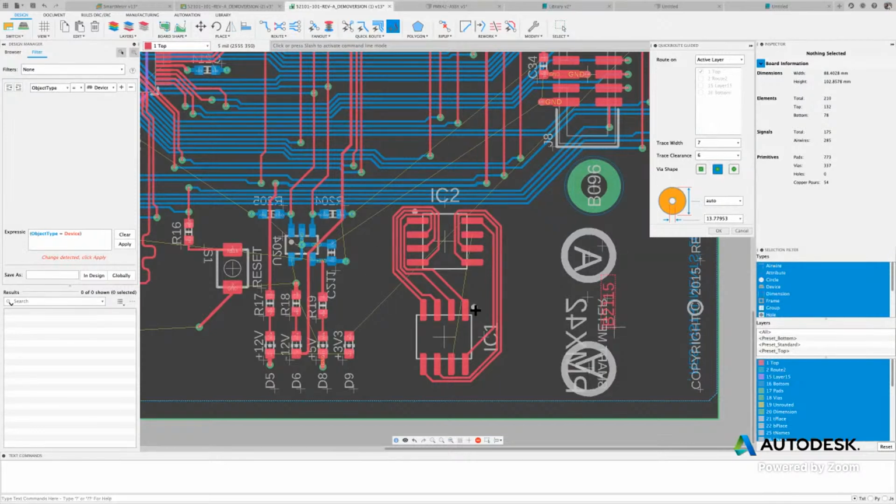And it routed these as well, influenced by the path that I was given. Now, this is kind of cool. If you have components that are in the way and you have a group of traces that's a straight shot, and instead of breaking through other components, you wanted to follow a path through an outline of a board, that way it avoids any other components. This is actually a really cool tool to be able to use.